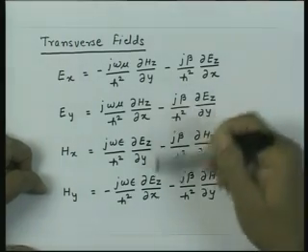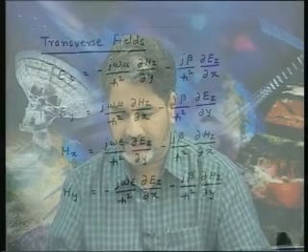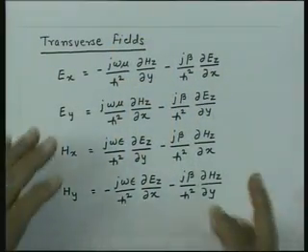So, with this general development for the propagation of a mode inside a waveguide, now we are prepared to take up very specific cases, and as we saw there are two types of mode which can exist, the transverse electric mode and the transverse magnetic mode. We also saw a special case which was the transverse electromagnetic mode, and now we take a very specific case, that is what is called a rectangular waveguide.